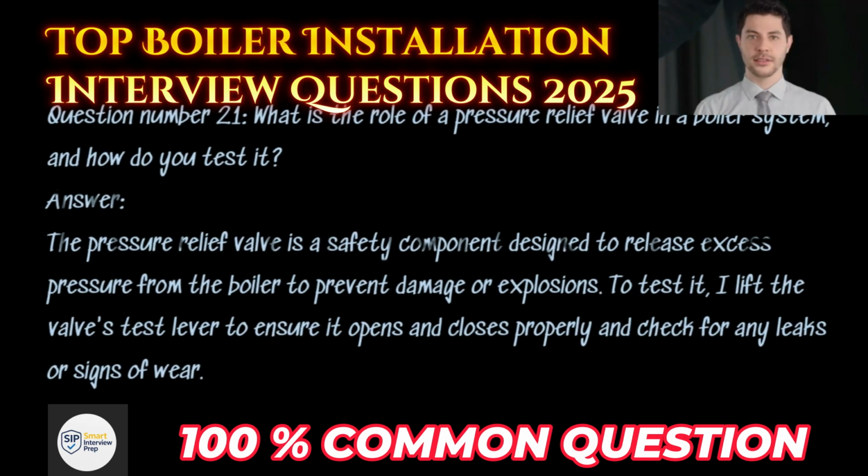Question number 21. What is the role of a pressure relief valve in a boiler system, and how do you test it? Answer. The pressure relief valve is a safety component designed to release excess pressure from the boiler to prevent damage or explosions. To test it, I lift the valve's test lever to ensure it opens and closes properly and check for any leaks or signs of wear.